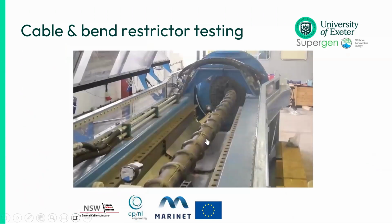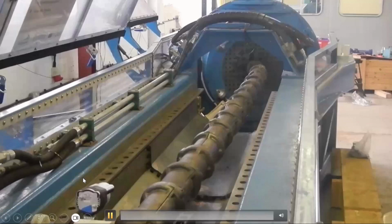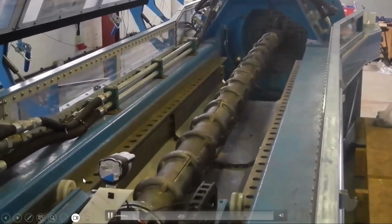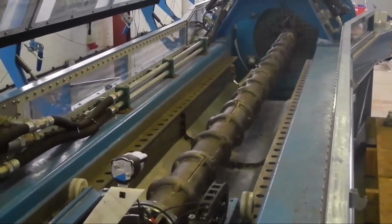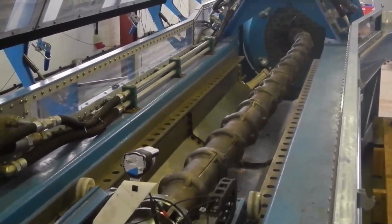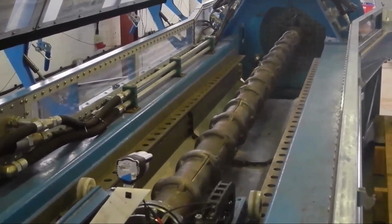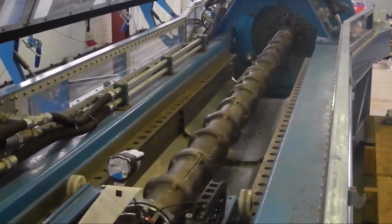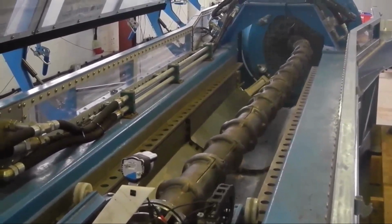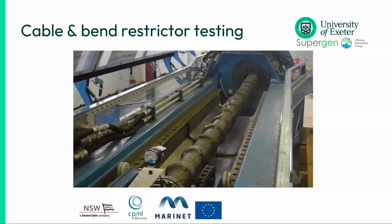There should be a video for it as well. So this is what we call a regular accelerated test. Each of those swoops is basically one full tidal cycle, swinging the cable from one side to the other. So we were trying to replicate about 60,000 cycles to replicate what these cables are likely to see over time.